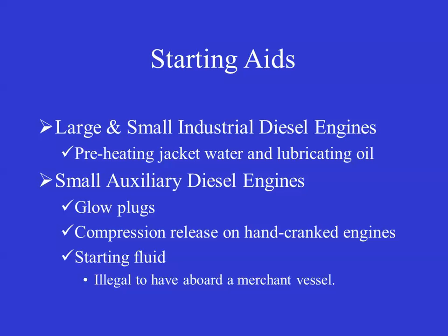But ether is very combustible. That's why you're squirting it in. It will ignite at a lower temperature in the cylinder. The problem with that is they've had cases on ships in an emergency, with people in the lifeboat, where someone sprays too much ether into the engine, and it will literally blow the head off the engine, and you don't have that diesel for an emergency situation.